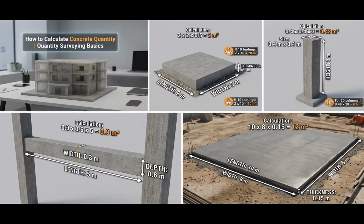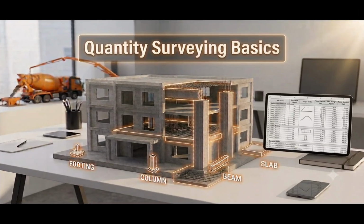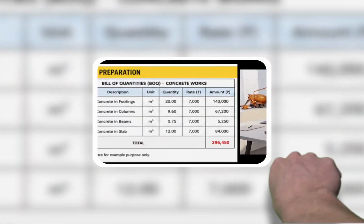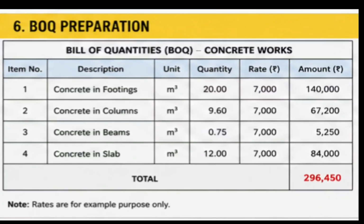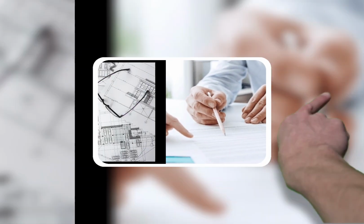After calculating the quantities for all structural elements, the next responsibility of a quantity surveyor is preparing the bill of quantities, commonly known as the BOQ. A BOQ usually includes description of the work, unit of measurement, quantity, rate, amount. Accurate quantity calculations help in material planning, cost estimation, tender preparation, and controlling project costs.